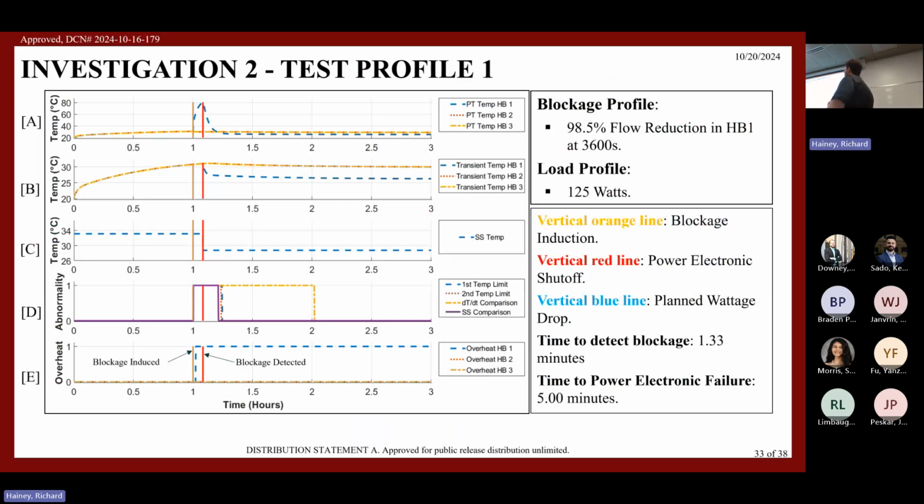Now, we wanted to detect this blockage occurring and potentially perform actions to mitigate it before the cooling block, or the emulated converter essentially, reaches this point. So using our digital twin system, it can detect the presence of a blockage well before the temperature in the converter reaches the dangerous 80-degree Celsius threshold.